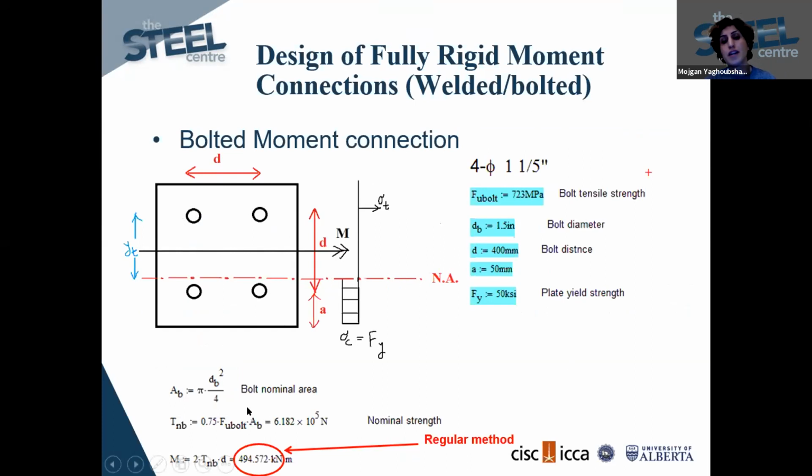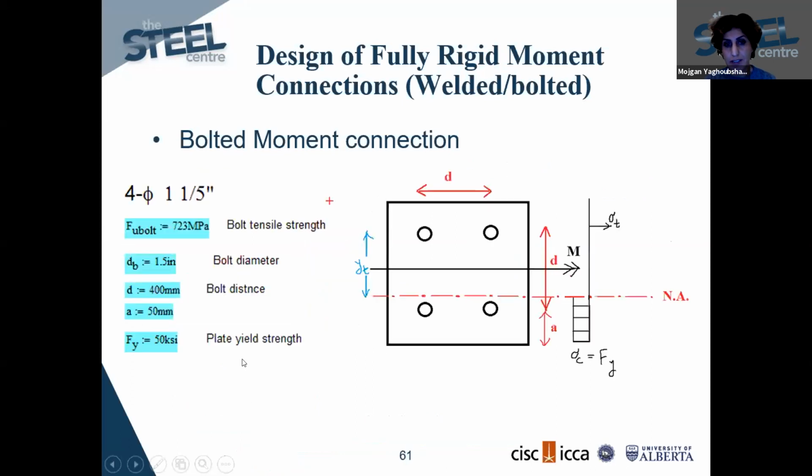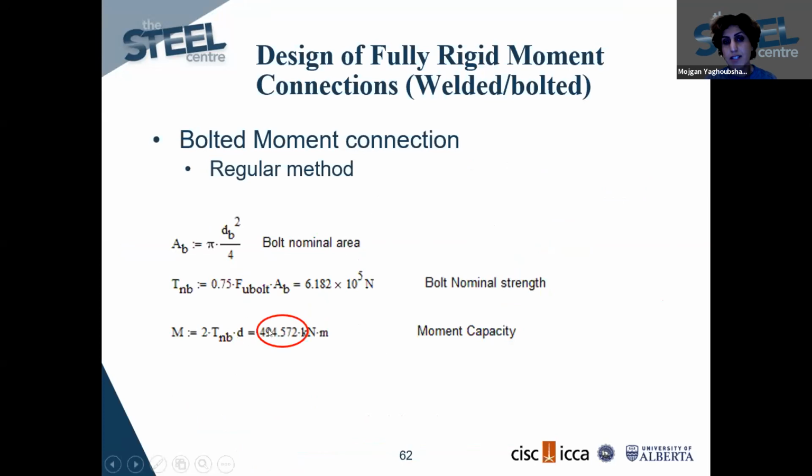If we use the traditional method, this is how we calculate the capacity of that bolted connection. We just rely on the capacity of the bolt.